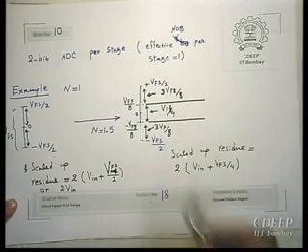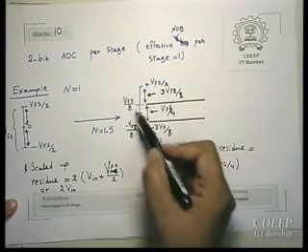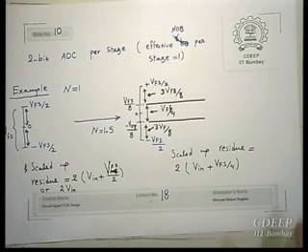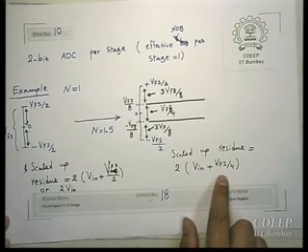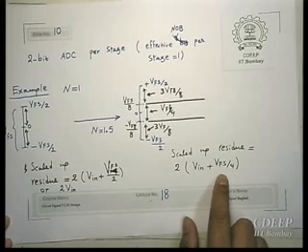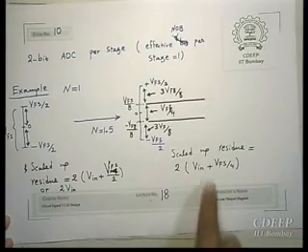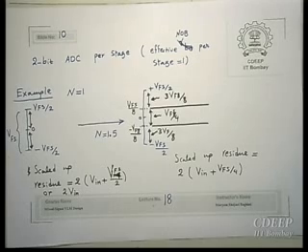So we have 3. Whether it is less than minus V full scale by 8, is between V full scale by 8 and minus V full scale by 8, or above V full scale by 8. So why are we adding V in plus V full scale by 4? Because it is 2 bits. So eventually we could have done that, but we are multiplying by 2. Now what it does is that if your residue tries to become very negative or very positive, that is the reason next stage will suffer. So it will try to return it back to its original value.